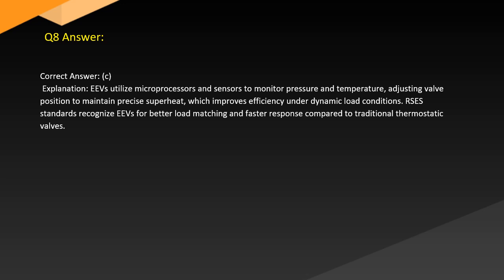Answer. Correct answer: C. Explanation. EEVs utilize microprocessors and sensors to monitor pressure and temperature, adjusting valve position to maintain precise superheat, which improves efficiency under dynamic load conditions. RSES standards recognize EEVs for better load matching and faster response compared to traditional thermostatic valves.